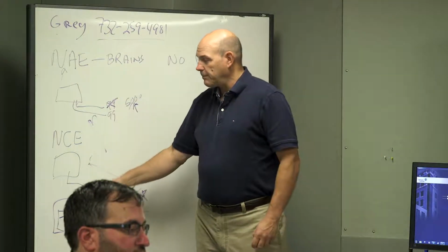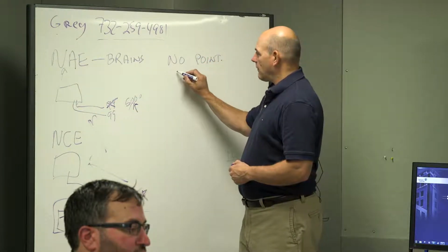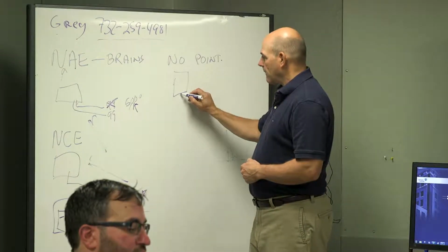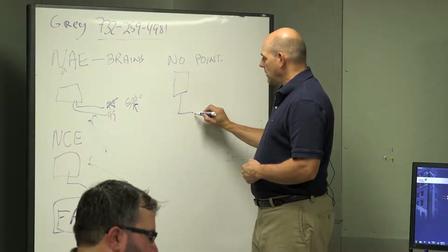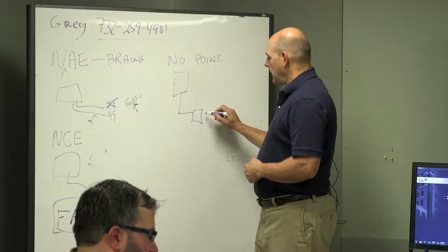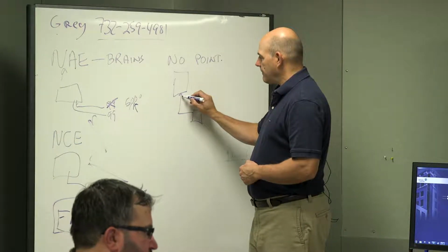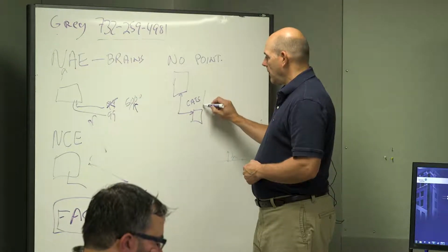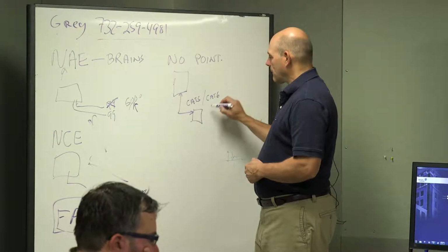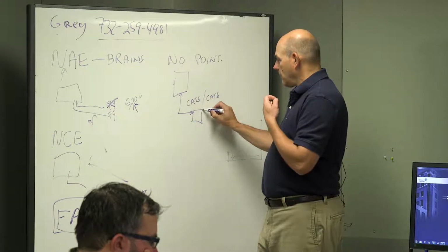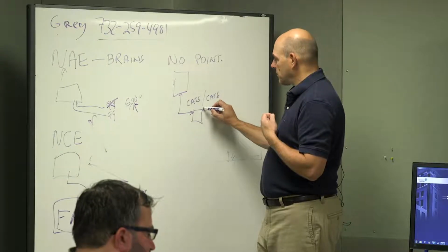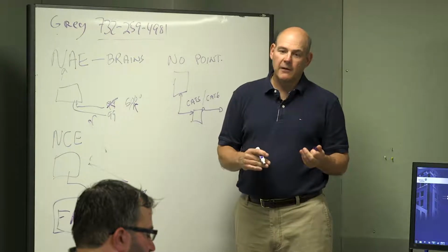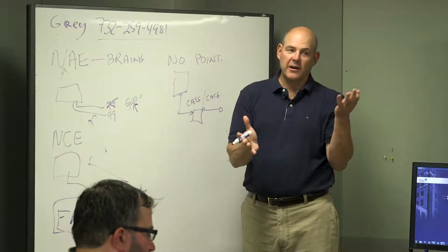So those are your big panels here. On a network diagram, you're going to have your computer, which is currently in the BMS room, your server. We're going to run communication cable to these main panels, which is usually Cat5 and Cat 6. Right? So they're going to go here, they're going to hit through a network switch. There might be a network switch in here. So you have to know how your network is run. And eventually we're going to get a nice riser diagram and go through that.